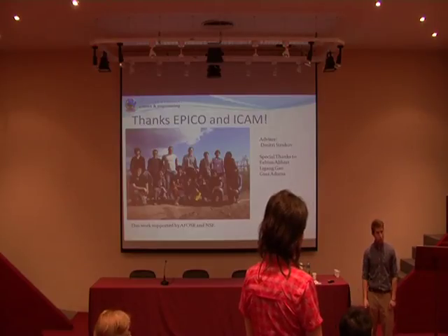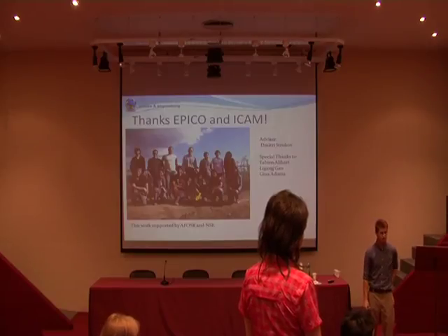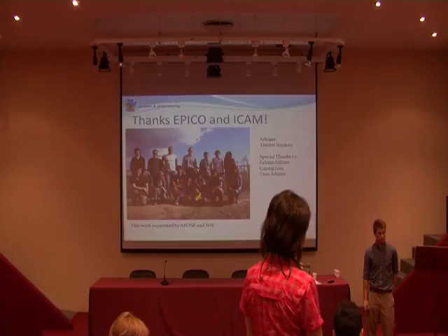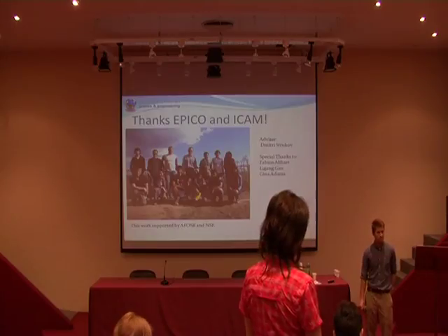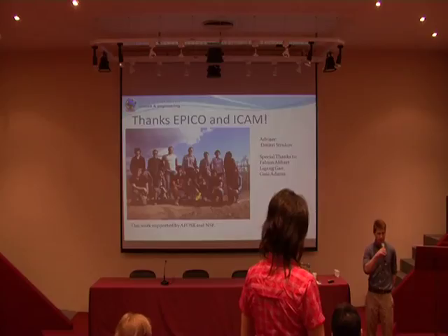But that would mean that the surface is completely flat. As soon as you start to crystallize, you will see these islands on the AFM pictures. So this is always the first hint that you start to crystallize, if your surface becomes more rough. So you don't have to do XRD, you always get some sign from the surface. All right, I'll look into that.